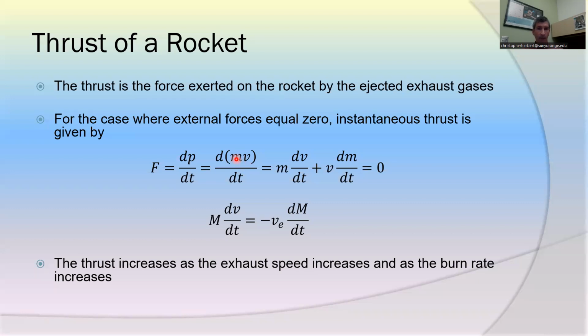So normally, if mass were just constant, as we've been using in most systems, we could put mass out in front and then just take the derivative of velocity with respect to time, and that would give mass times acceleration. But in taking this derivative, I have to basically treat both of these functions as time dependent, and that's going to give me two terms.